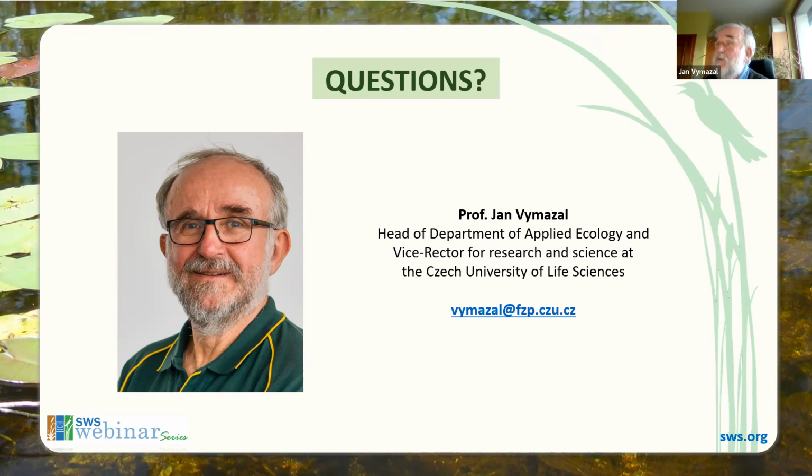Well, we don't have petroleum wastewaters in our country too much. We have some refineries. However, there are some very fine examples of constructed wetlands which were built to treat wastewaters from the drilling sites. I think that the best known is that in Oman, where is a wetland about 4 square kilometers planted with Phragmites, and they combine it with evaporative ponds. So at the end, they do not have too much inflow and they use it for irrigation.